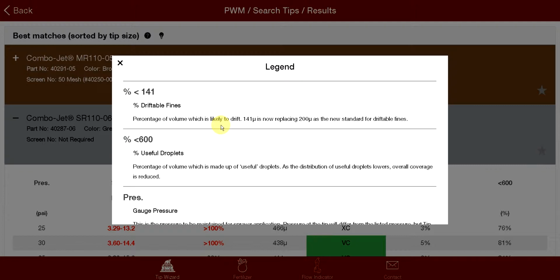Think of it this way: the small droplets only spray out of the spray tip and can only travel so far, typically within that 3 to 6 inches. And at that point, they've near stopped. There's no more velocity behind them. The only way they're coming down to target, your crop or your weeds, is sprayer speed, wind speed, or gravity, to which gravity has very little control because there's very little weight or mass to those droplets.